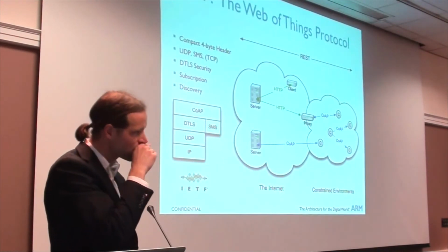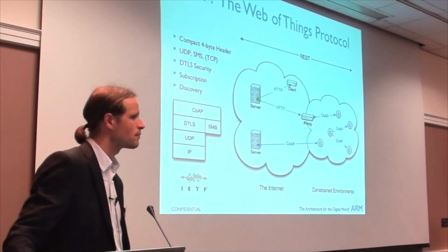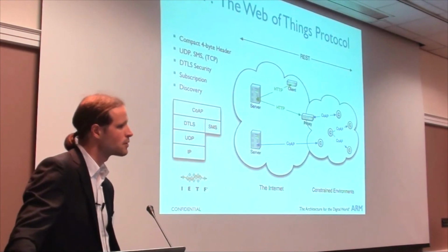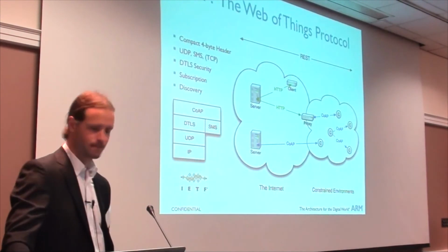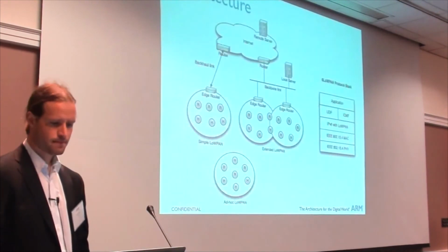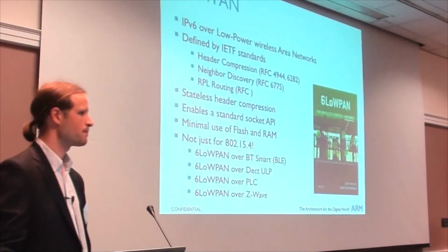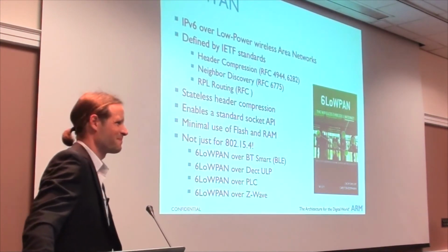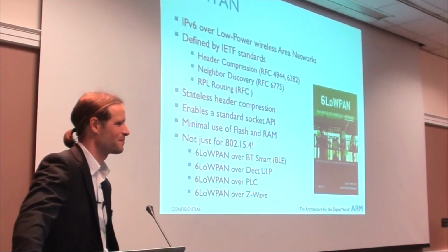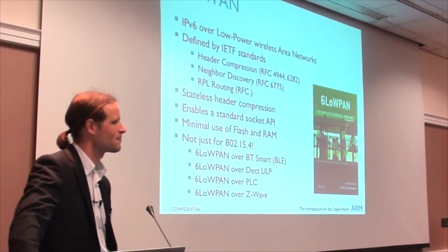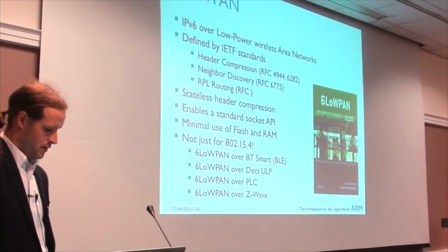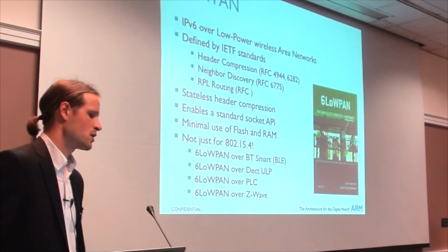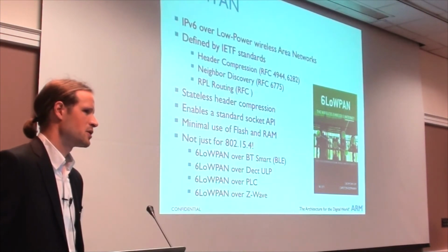Yes, just a curiosity question. I like 15.4 a lot, but to me what's really exciting about it is the sub 1 gigahertz. Absolutely. You've got this great range, lower power, more than enough bandwidth with 20 megabits per second. It's great. In Europe, we got the short end of the stick because we have one channel compared to 15 in North America. But yet, I see very little 1 gigahertz hardware out there. I've always used the 1 gigahertz. But what percentage of the market do you see today in that 1 gigahertz spectrum? Because that's what's really interesting to me.